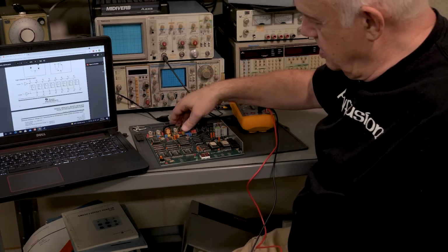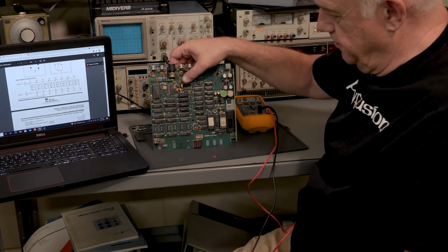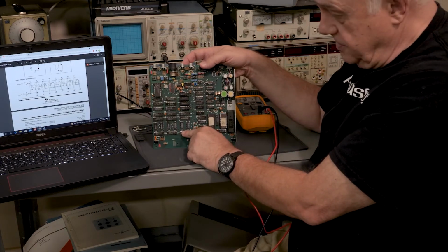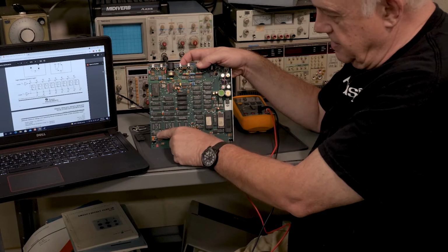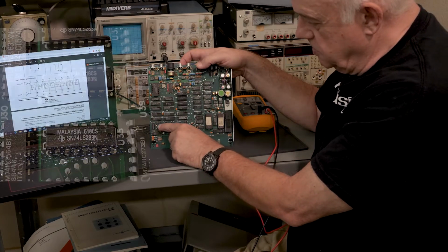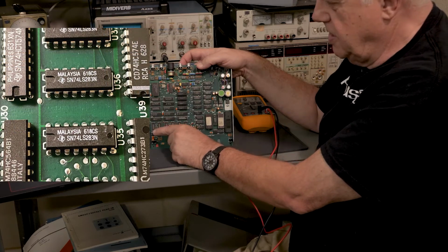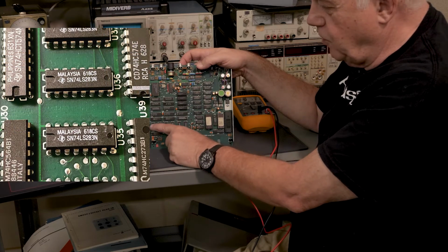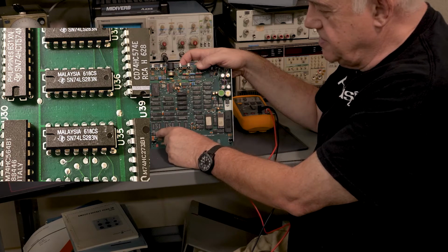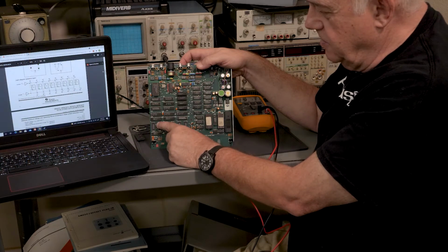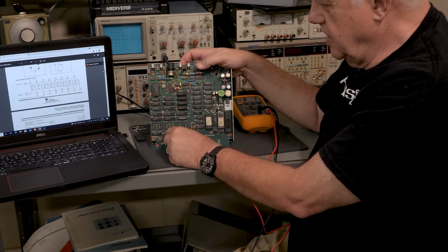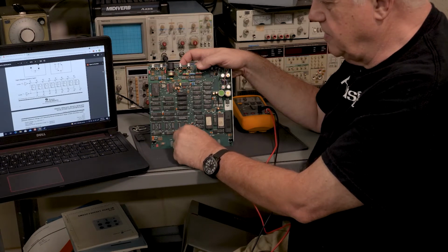So if we look at the board down here, if my theory is correct, that means that this flip-flop probably is going to connect to these 2 chips, which if you check, they're 4-bit adders. So there's 8 bits here and 4 and 4, that's 8. So this is a group of 8. And if this is the input to the adder, well, there's another register right here where the output could go. And that's repeated here. It's repeated here.